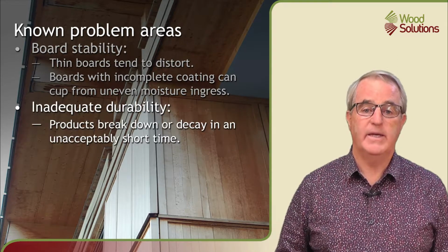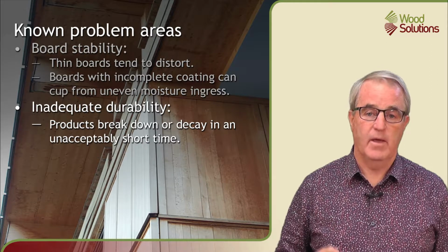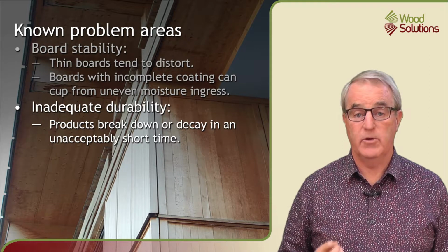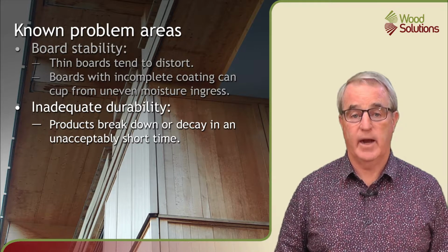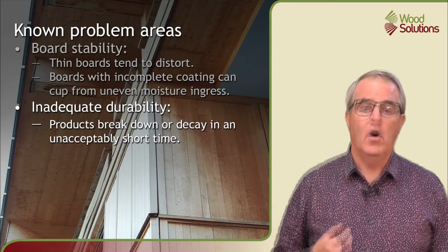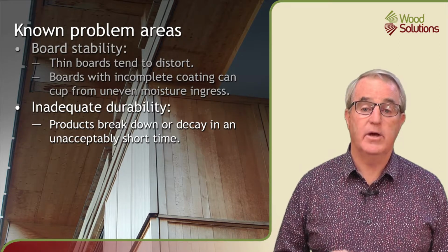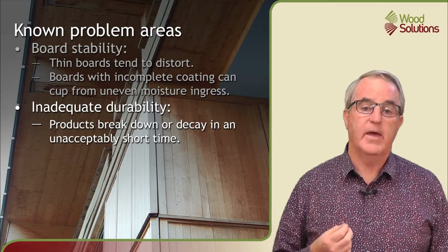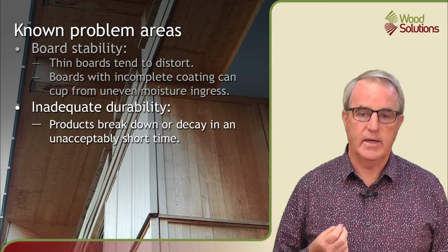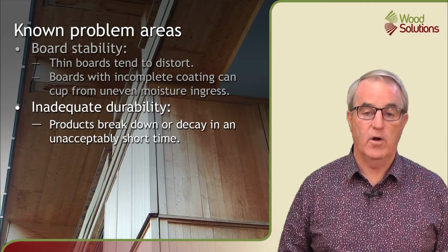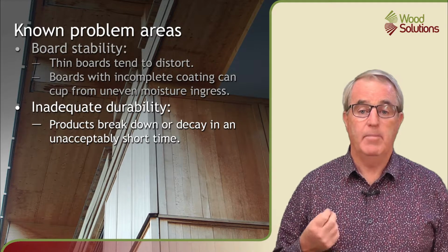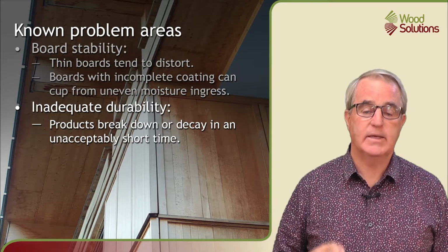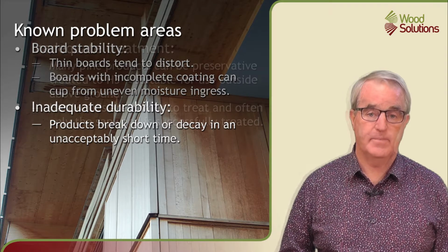The next problem area is inadequate product durability. First, the natural durability of the boards may be inadequate, or the material may break down or decay in an unexpectedly short time. Also, some products are designed to stand being wet on a construction site for several months, but they can deteriorate if they are in a high moisture environment for a long period of time. Particle board flooring, wall framing and nail plated elements are examples of this type of product.